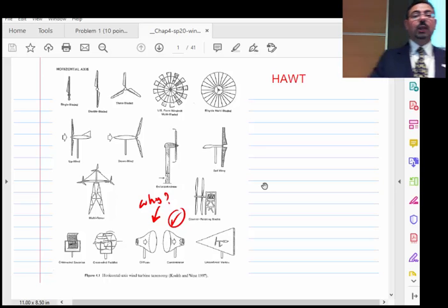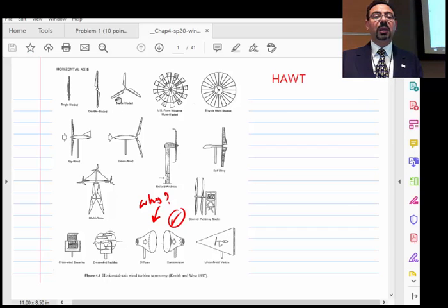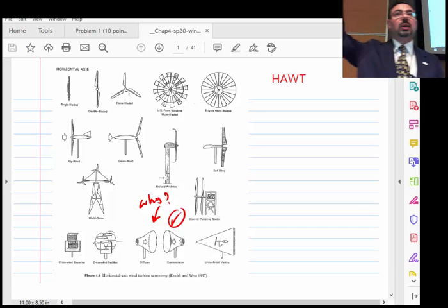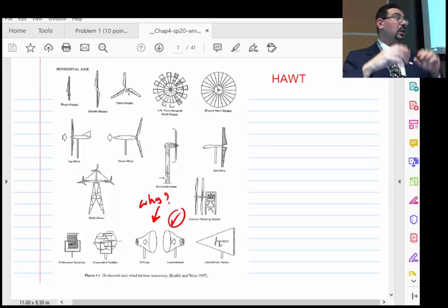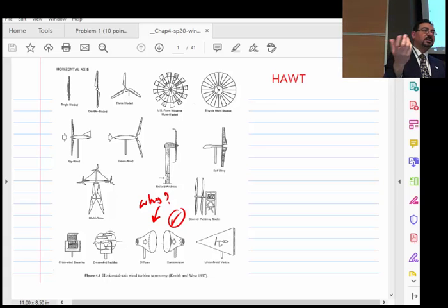Okay? They rotate, and actually it's really funny the way they rotate, because obviously they will have the generator on the top. The generator will be sitting behind those plates, and that generator generates electricity, and so there must be a cable coming from that generator, and that cable comes into the tower all the way down to the ground so that it can go to the network. So do you see a problem now with that cable? It can spin itself so that the cable will get basically stuck.